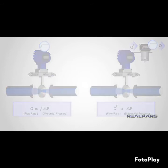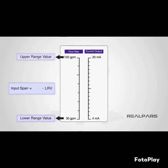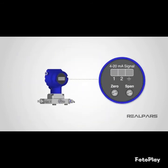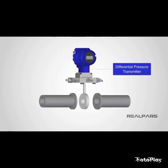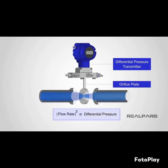Let's review what we've discussed. An instrument is calibrated when its output corresponds to a specific input across a specific range of inputs. The input span of an instrument is simply its lower range value subtracted from its upper range value. Zero and span are the names of the adjustments made in order to calibrate an instrument. A common method of flow measurement is done by using a differential pressure transmitter across an obstruction such as an orifice plate. The differential pressure across an orifice is proportional to the square of the volumetric flow rate. Therefore, we need a square root extractor.